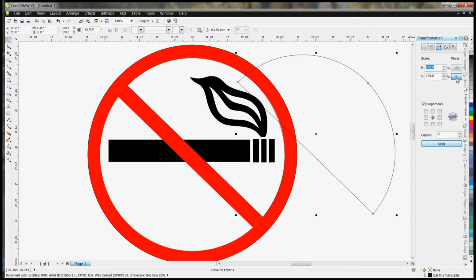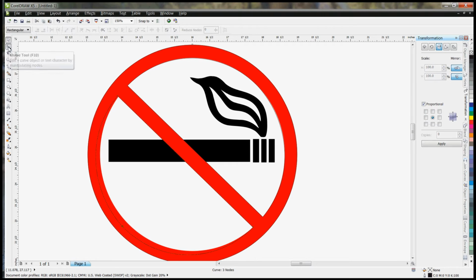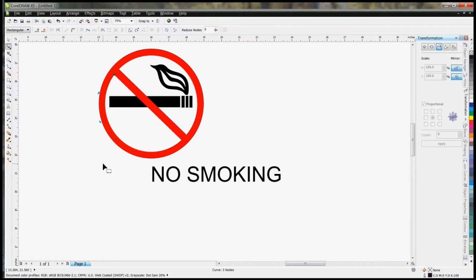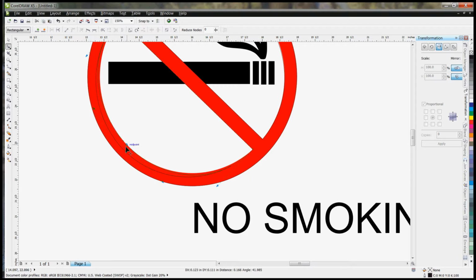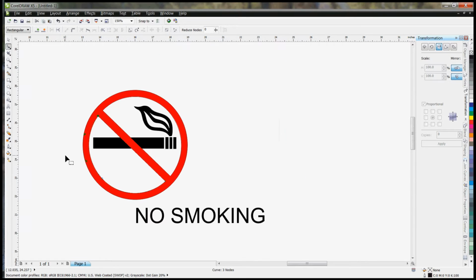At this point, I'm going to turn Mirror on for both horizontal and vertical. I don't want any copies. Hit Apply, and it'll mirror it so that I can just drag it down here and put it into place. Well, it looks like the size isn't exactly the same on this image, so I'm going to once again go into the shape tool and just drag the points till it matches. Go to the different nodes, like this one right here, and then I'll just adjust these lines a little bit. It just keeps you from having to completely redraw it if you don't want to. In this case, it would have been probably just as easy to redraw it, but I wouldn't have gotten to show you another technique.